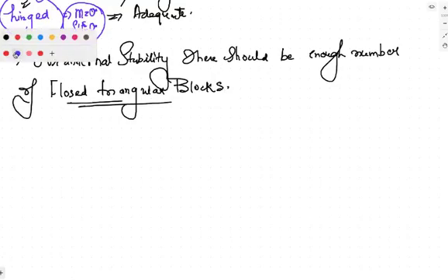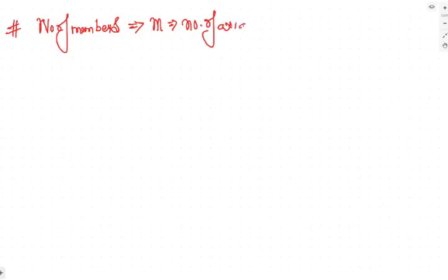ठीक है, अब मेंबर्स की बात करते हैं. अब एक बेसिक सी बात करते हैं, कॉन्सेप्चुअल बात करते हैं. रटने की जरूरत नहीं है, सब कुछ कॉन्सेप्ट से हो जाएगा. रटोगे तो कंफ्यूज हो जाओगे. बहुत सारी चीजें हैं यहाँ पे, बहुत सारे फॉर्मूले हैं यहाँ पे. देखो, as I told you, there should be enough number of members and each member will be carrying axial force. Let's say the number of members which are present in the structure is M. It means their number of axial forces will be the same. जितना member होगा उतना axial force होगा. So we are considering there are M number of members, and so the number of axial forces will also be equal to M. Fine. Pin jointed केस की बात कर रहा हूं मैं.